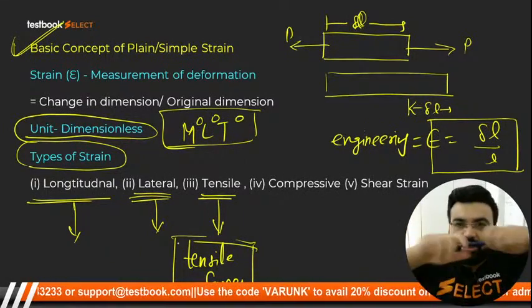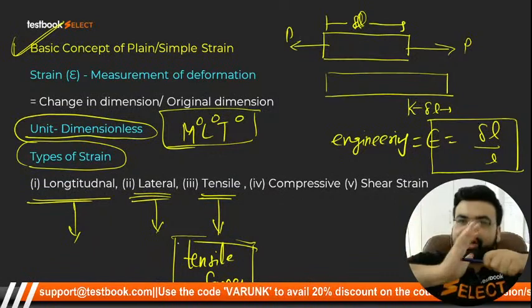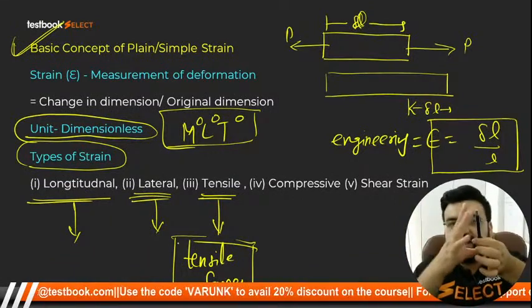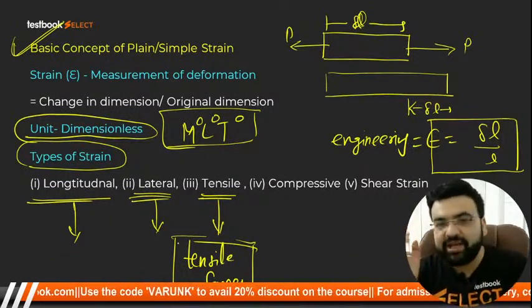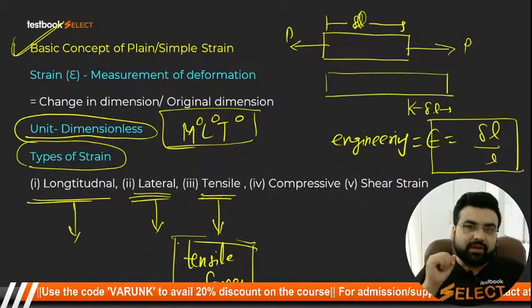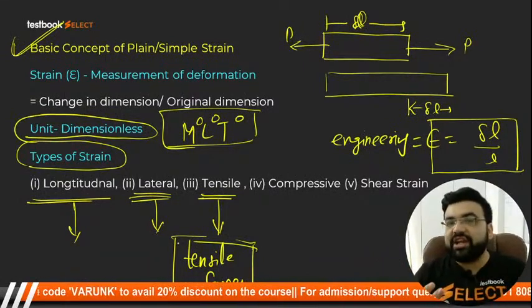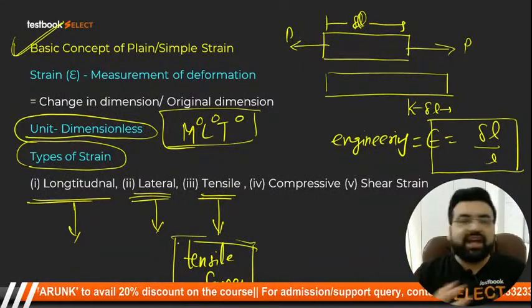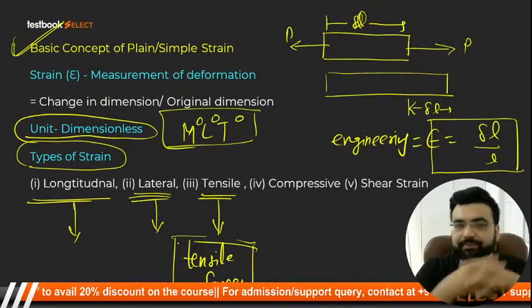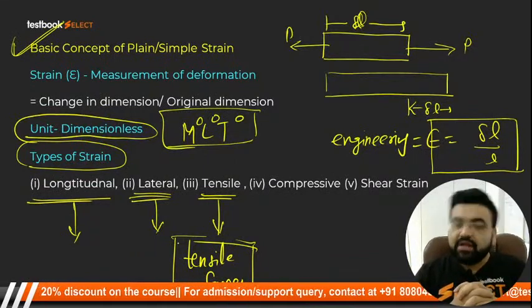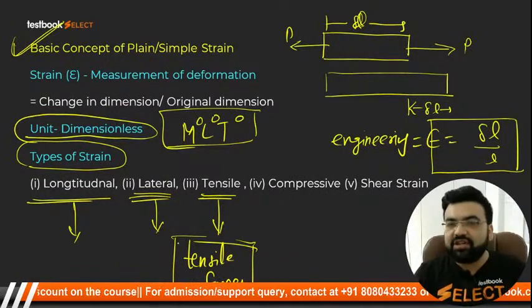And what is a compressive force? Which you are applying towards this body. If you are pushing it from here, the length might decrease. So that force is said to be a compressive force. And the strain getting generated because of the compressive force is said to be a compressive strain. Clear? Similarly, students, you might also have a shear strain.